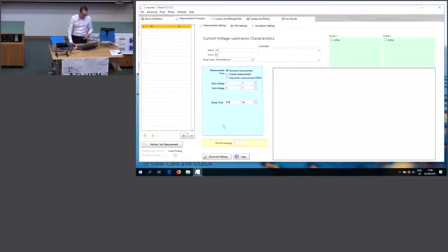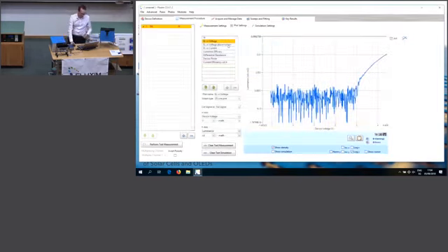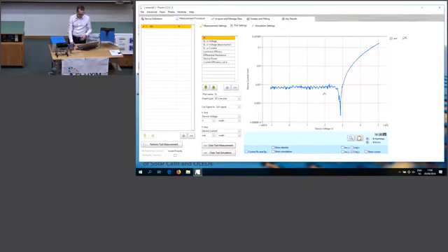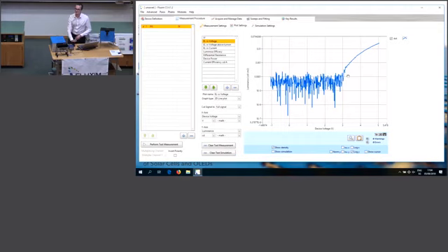So here you can define how fast the ramp is. Let's say 600 milliseconds, and I just quickly perform a test measurement. It now measures a whole ramp, and it goes quite quickly. So you see, this should not be in log. This is the current, and this here is the electroluminescence signal for the OLED, just a quick test.